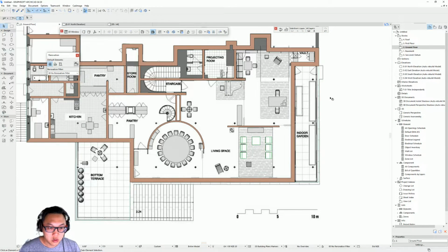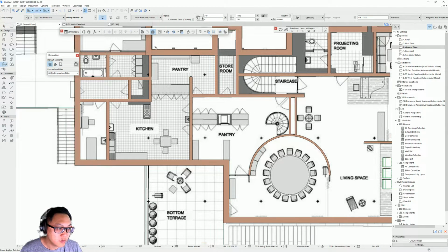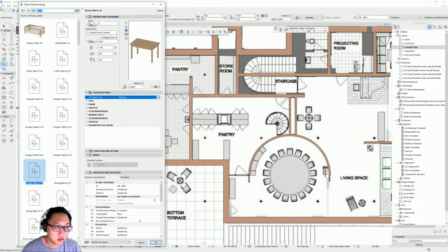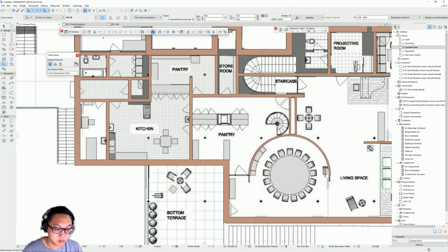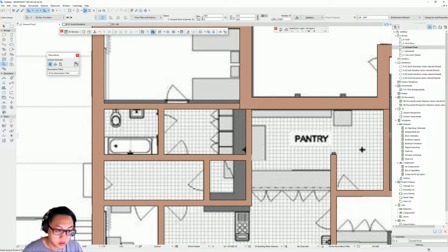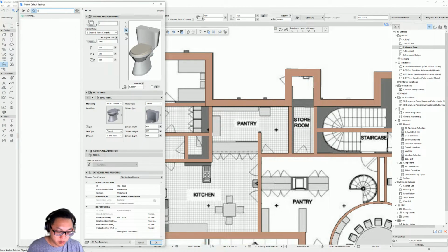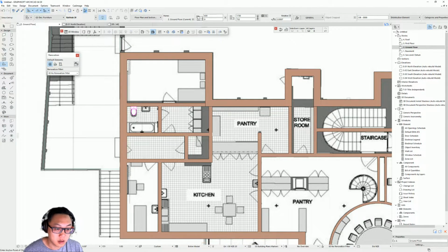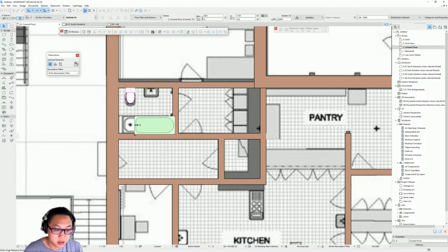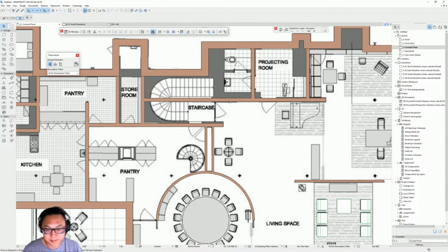So you can do that for all of the objects. If you type, let's say, WC, I'll get the toilet. Press OK. It's up here, and what do you have? The bathtubs. Control D to move it around, and you can do the basin.